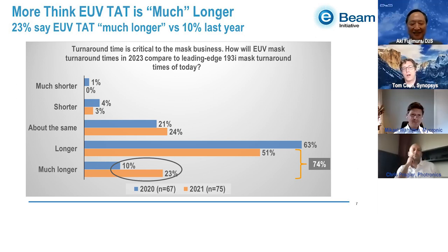Well, for us, working with the customer to tape out a layer, it's a question of the total turnaround time for all the masks necessary to get that layer through. Even if you're doing double patterning on 193i, that could be faster. But if you have to do 2 or 3 of those, then the overall time is really a question of how much longer this longer bar is.